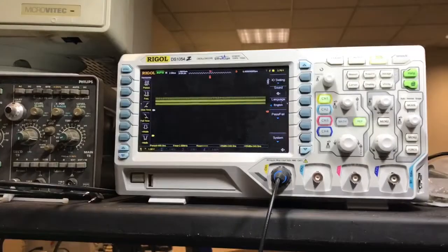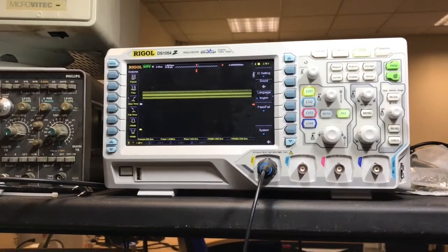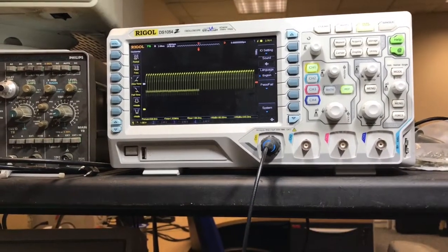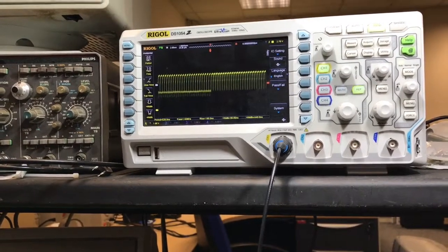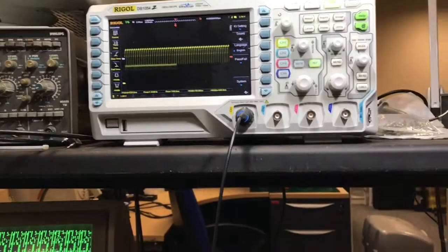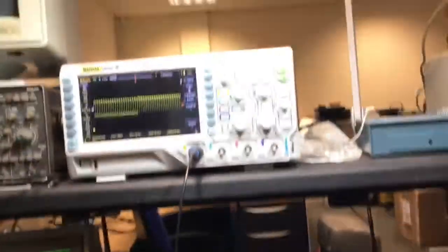And you see there, it's just stuck high. So the pin 5 is doing absolutely nothing. But if I go to pin 6, you can see that's trying to pull low, because that's the inverted version of pin 5. We're going to stick another chip up, we'll stick a 74 over the top of that and see what happens.